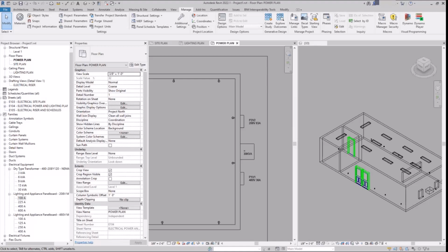Right. If I'm understanding you correctly, you're saying if there's no 480 volt equipment on there, but we have a 480 volt utility transformer, do we still have to have a 480 volt panel board? Correct. Is that your question? Yeah. Okay. So in that case, if there's literally no 480 volt equipment on site, then I would set a disconnect here and then feed that directly to the transformer.